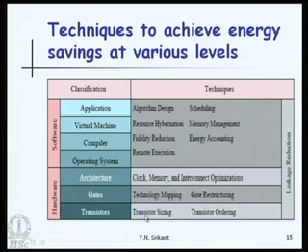At the transistor level, the size of the transistors and the transistor ordering actually control the energy consumption. At the gate level, technology mapping, which particular technology, and the gate restructuring control energy consumption. At the architecture level, clock, memory and interconnect optimizations, which we are going to see later, will control power consumption and energy consumption. And then with applications, virtual machines, compilers and operating systems, we have a host of techniques which interact with each other. That is the reason why there is no separation between these techniques. So, we can do better algorithm design.